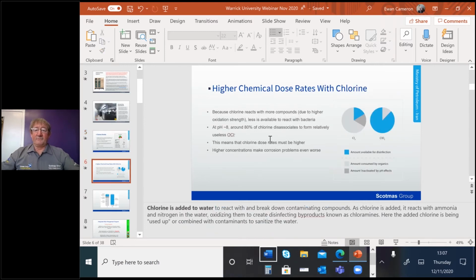As we can see here, the chlorine dioxide which is actually available to do the kill is affected by the bioloading, but not to the same effect as it would be if we were using just, for example, chlorine. There's far more of the chlorine dioxide available because it really is looking to rob electrons, and it's very selective in the way it does that, and it doesn't combine as it would with chlorine. So there's far more available biocidal effect than with other types of products such as potassiums or hydrogen peroxides or peracetic acids, etc., which other people have tried in the past.